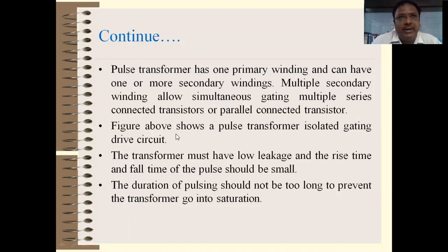So in that rectifier, two diodes conduct at the same time. If we replace the diodes with SCRs, because it's a controlled rectifier, two SCRs can conduct at a time, so we require two triggering pulses of the same timing. At that time we use a pulse transformer with two secondaries. In three-phase converters, we are required to turn on three thyristors at a time, so we require three pulses. At that time we can select a transformer which has three secondary windings. So these are the requirements.